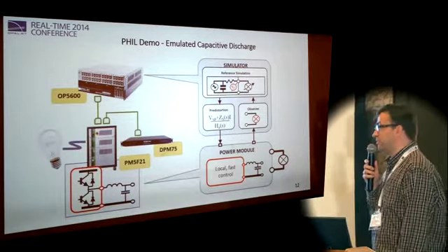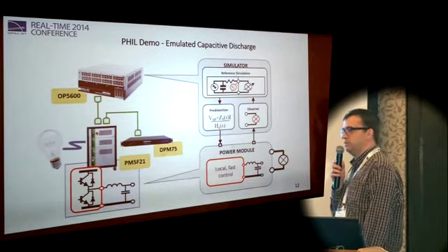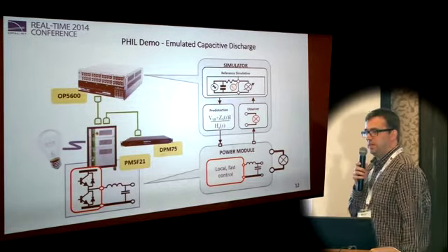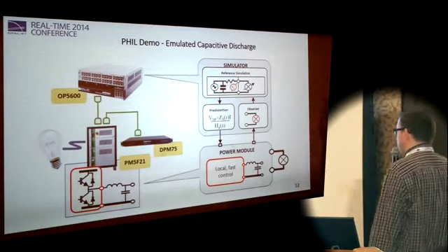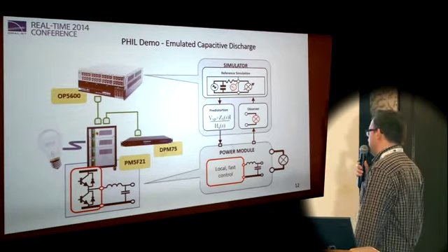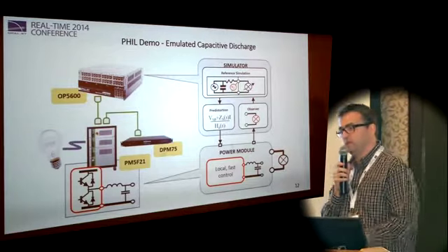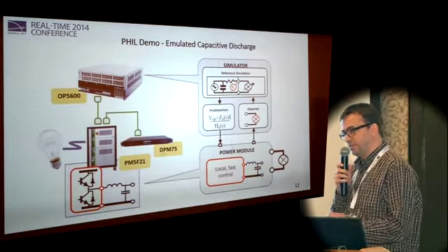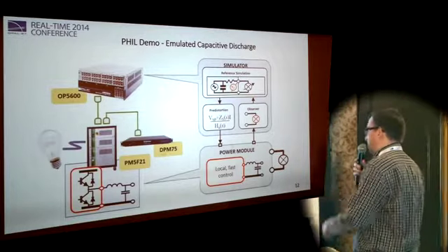Why? Instead of treating the device under test as something completely unknown, in the simulation we insert the knowledge that we know it is a light bulb. A light bulb is a heat varying resistor. So what do we do? We use the measurements that we get from the system to identify the characteristics of the light bulb. Those characteristics we use in the real-time simulation.